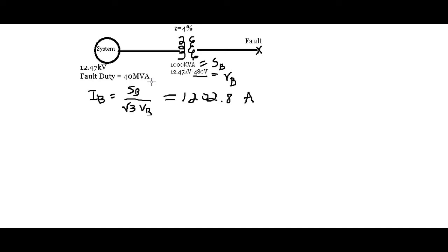And we can use this fault duty or primary MVA short circuit to calculate the percent Z source.